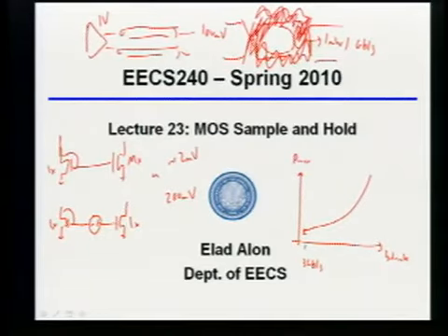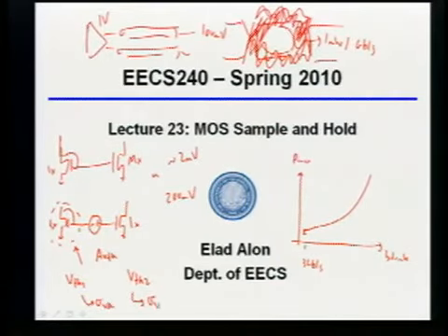Okay, so let's pretend that I somehow wanted to match this to some, let's say, non-existent but other transistor that has no variation. If I looked at the mismatch between that one and this other non-existent perfect transistor that has no variation at all, how would I change the AVTH parameter to account for the fact that that other transistor has no variation in it at all? Divided by 2? Is it divide by 2? Root 2. Yeah, there we go. It's square root of 2, right? Because I'm taking essentially something like VTH of transistor 1 and comparing it to VTH of transistor 2. Each of these has some random variation with a certain sigma associated with it, right? So remember, you have to do root sum squares because unfortunately subtraction is the same thing as addition in terms of random numbers, in terms of variances. So effectively, you just have an AVTH that's square root of 2 smaller than that, right?